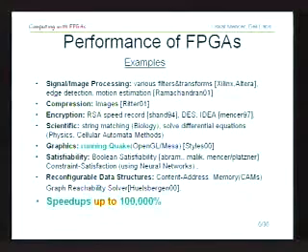So if you have this model, you have a lot of data, there is a little algorithm that has to modify this data, it's relatively straightforward to simply stream this data through the FPGA and get very high throughput. This way you also get around the latency problem that I talked about before, where you actually run at 5 times slower clock frequencies. So if you have basically pipelining, you can get around that problem for many applications.